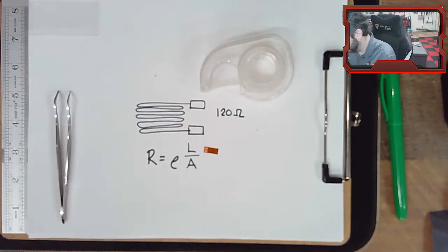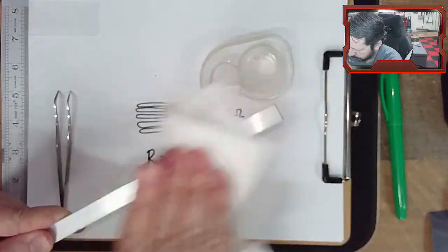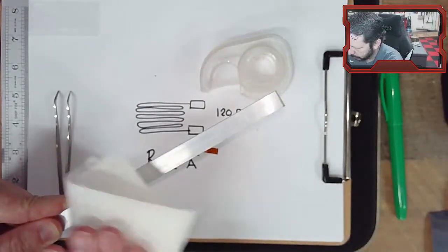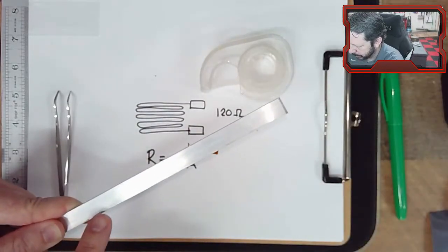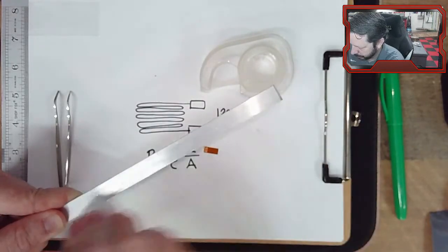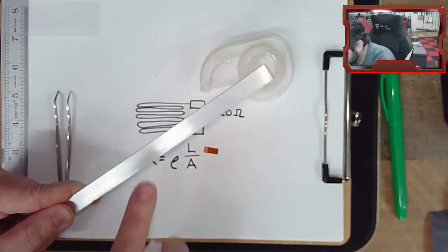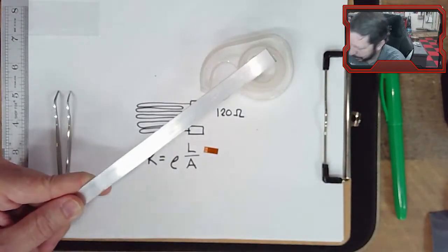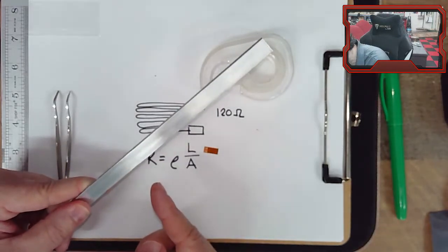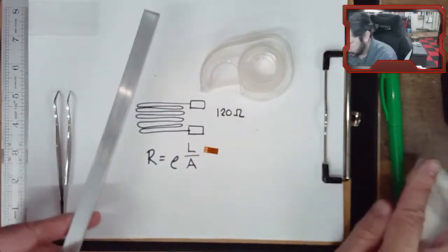I'm going to squirt it one more time with IPA and then wipe it down. And notice I'm only wiping in one direction so that if I drag any material into it, I'm dragging it from a clean spot. I'm not smearing it all back and forth. All right, so now, it probably doesn't show up much on camera, but sitting here looking at it, I've got a cleaner spot than other spots.